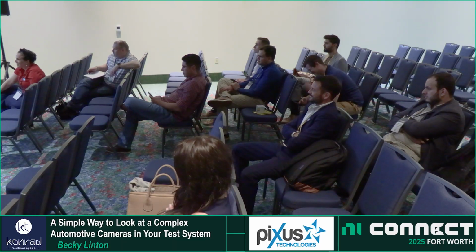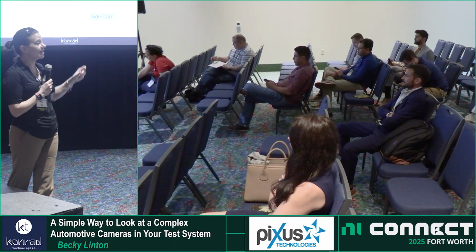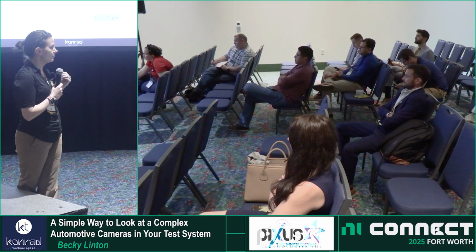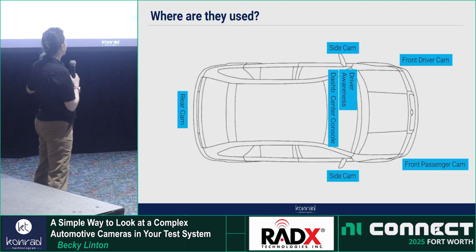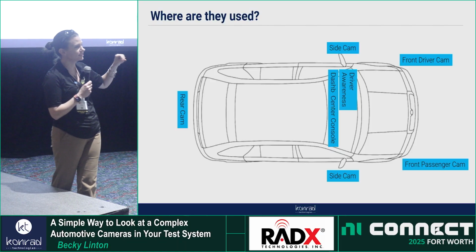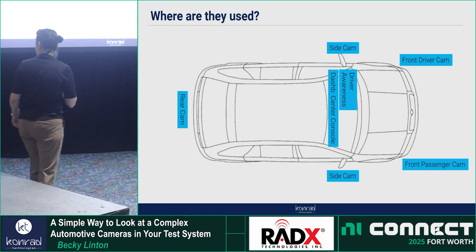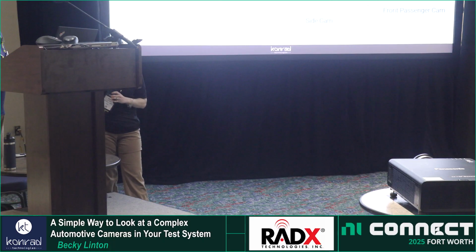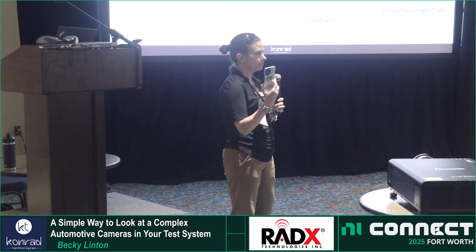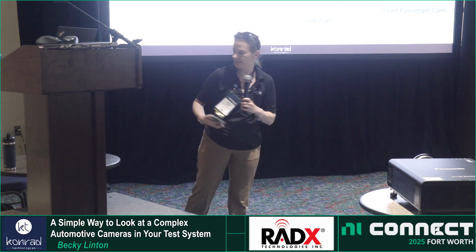So in your pocket, your cell phone has a camera in it. That is not a SerDes camera, but the technology behind it is the same. MIPI CSI-2 is the standard, which is behind how the bits get packed. When the automotive and robotics industries really started using the serializer and deserializer, they went a step farther. If any of you have ever done anything with CSI-2 cameras, there are cables between the camera and your PCB, but there's a maximum length of so many centimeters before the signal loss is too great and you lose the image.